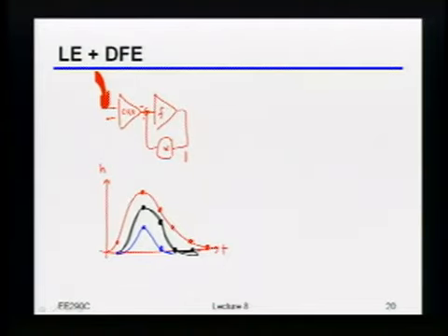So basically, here you could make the first pole of the equalizer half of what you would otherwise. That's right. Roughly speaking, yes. Now, it's not exactly a factor of 2 because it obviously depends on exactly the channel and things like that, but ballpark, that is indeed what it ends up being. And you can imagine if you cancel even more of these things, you may even be able to back off further, although for most channels, there are diminishing returns after that point. But indeed, there is about that factor of 2 that it buys you in terms of the bandwidth of that linear equalizer.